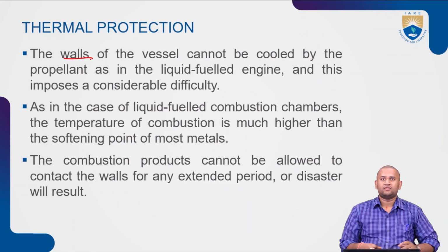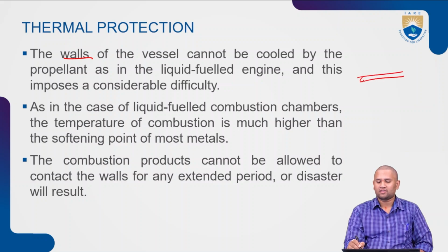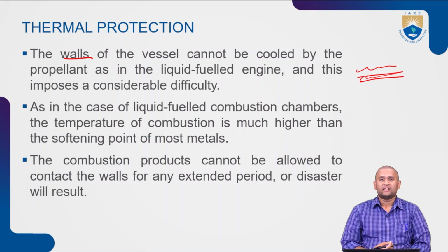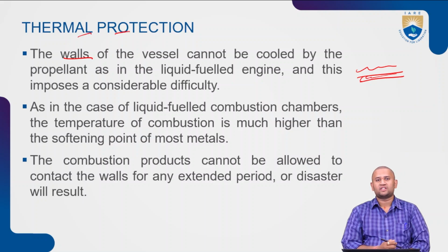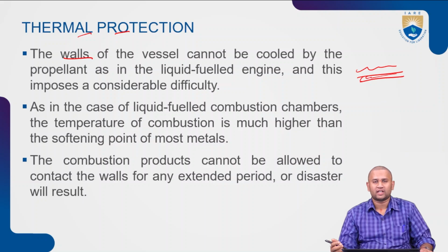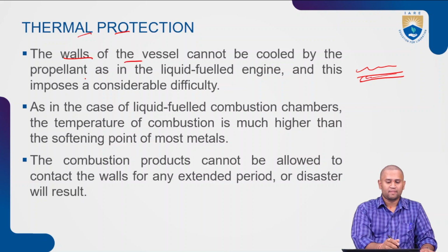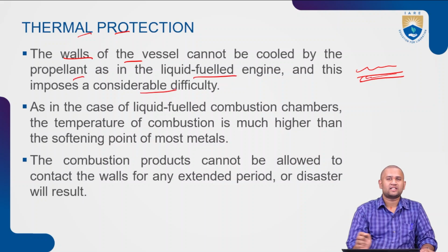Now, coming to my casing, as the casing will be in direct contact with the hot gases upon completely exhausting my solid propellant, we need some sort of thermal protection, right? Thermal protection to the walls to prevent the rupture of my combustor walls or my solid motor casing. Now, the walls of the vessel cannot be cooled by a propellant similar to a liquid fueled engine, and this imposes a considerable difficulty.